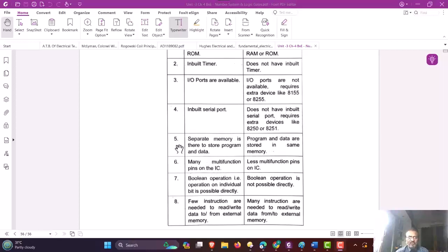Microcontrollers have on-chip memory for storing programs as well as data, whereas a general purpose microprocessor doesn't have this facility on chip. But a computer system can implement this with the facility provided by the central processing unit, which provides the interface of address bus, data bus, and control bus to hook up these peripherals externally.